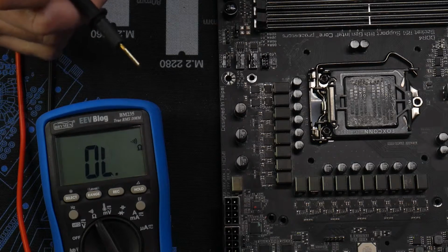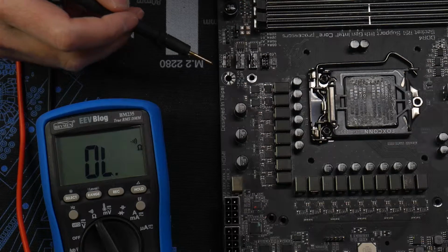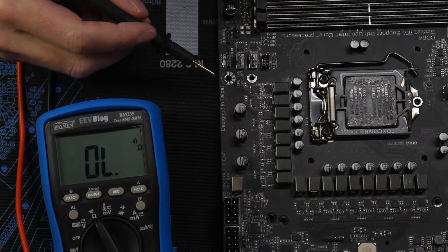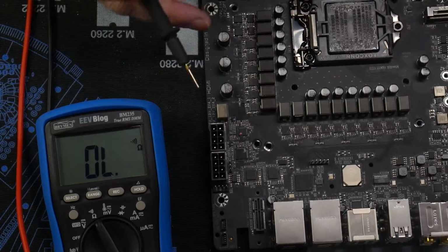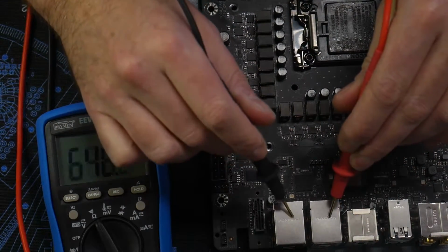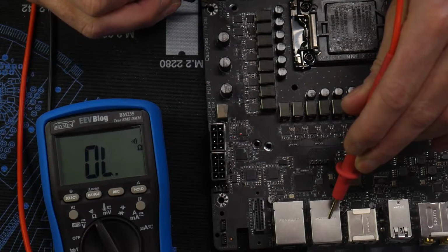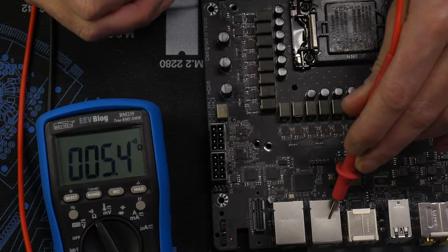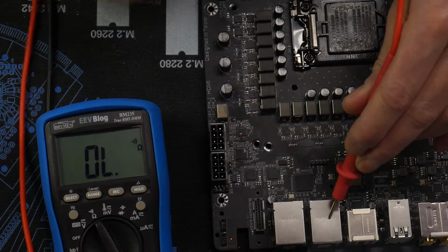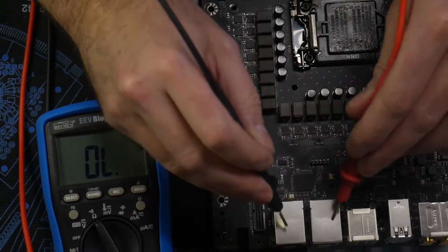That's critical because we're actually going to use the primary addressable LED header to find out what is what. And the most important part is finding ground. If I move the motherboard this way, a lot of things connect to ground. We have the I/O, then even around where the screw goes, we have ground points. So a lot of places are grounded on the board, and that's one good thing to know.